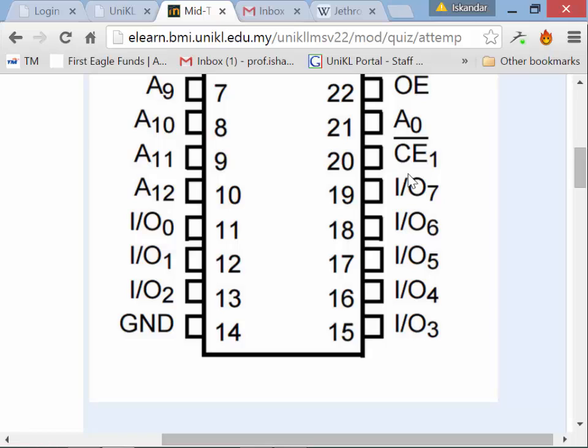Now, a little hint is that when we look at memory devices, they normally come in one of 3 different flavors. They're either by 1, in other words, you only have 1 output, or they're by 4, or they're by 8. So far, we've only talked about by 8. But if you look at a lot of desktop PCs, you might see 16 chips across there. Each one of those is 1 bit by a lot of memory locations. It might be 16 gig by 1.